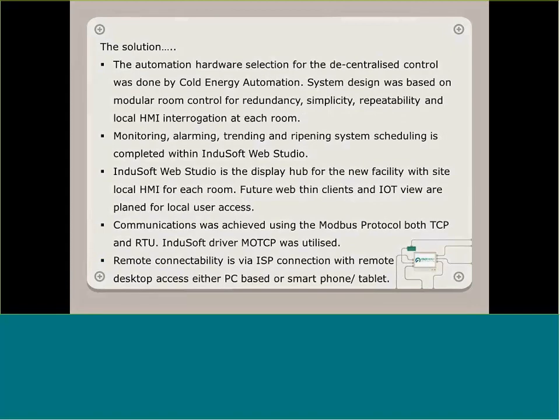The solution. The selection of the Indusoft MTX platform for the rooms ensured that the modular control brief with local HMI could be achieved. The PLCs allowed for a redundant, simple and repeatable system with commands accepted from the local HMI and Indusoft SCADA in real time. So for those people out there that do a lot of serial integrations, local HMIs and SCADA packages on the same networks can sometimes cause a lot of drama. So we found that worked really well.